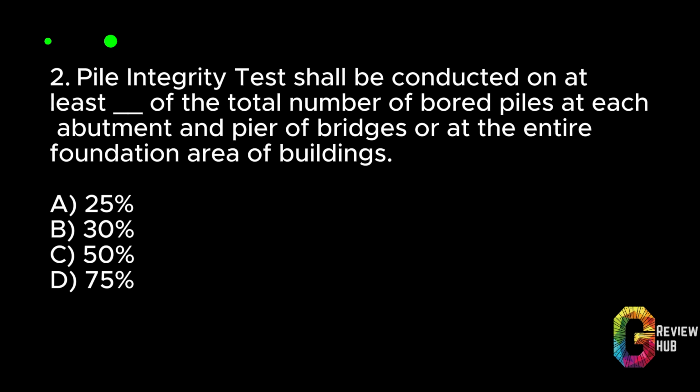2. Pile integrity test shall be conducted on at least blank of the total number of bored piles at each abutment and pier of bridges or at the entire foundation area of buildings. A. 25%. B. 30%. C. 50%. D. 75%. Answer: C. 50%.